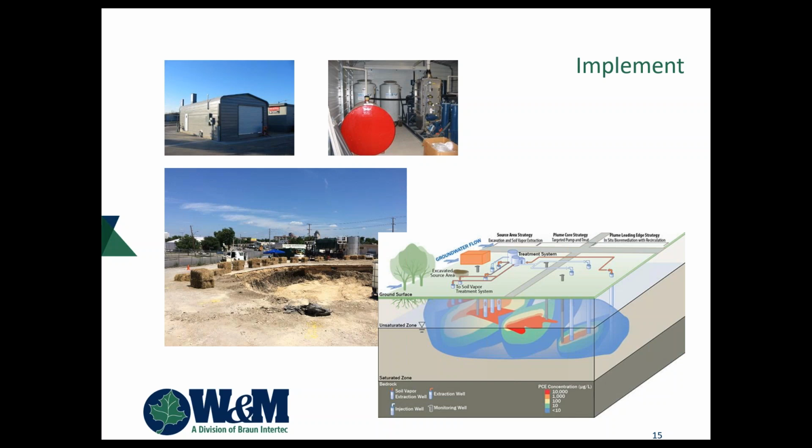of groundwater produced. That was a big benefit to us because on this site, we knew ahead of time going into it from some geochemical analysis that the site's dissolved iron was ridiculously high. So we knew the more water we had coming through the system, the more scaling we were going to have, and the more money we'd have to spend on scale control agents. So using this product increased our vapor, which also means we decreased the amount of fuel gas we needed on the thermal oxidizer and decreased the amount of liquid LNAPL coming off the oil water separator and ultimately going to